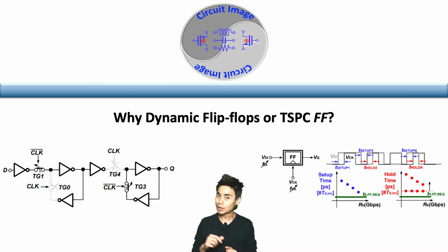Last time, we described the timing requirements of the flip-flop in the setup and hold time. In addition, we put the static flip-flops as an example to describe why the setup and hold time requirement is a must. After that, we provided the dynamic timing analysis, DTA, for the static flip-flops, which might be sufficient or not. Therefore, perhaps we may need to explore other dynamic flip-flops. For example, choose single-phase clock TSPC flops.